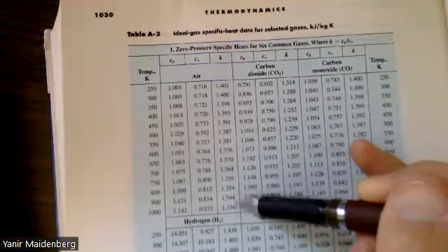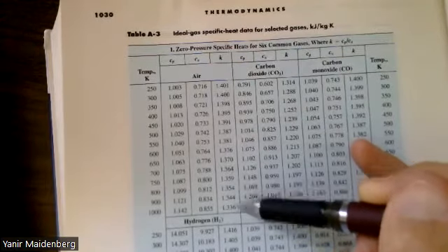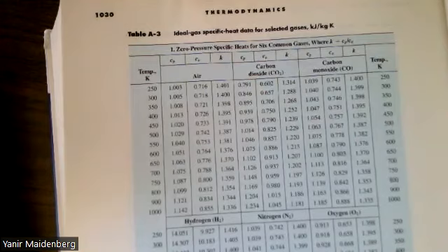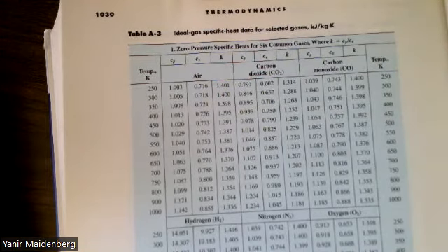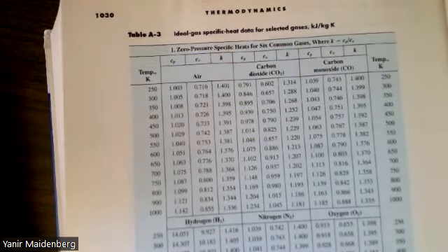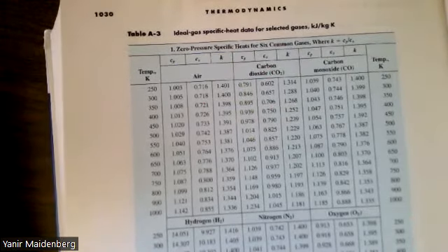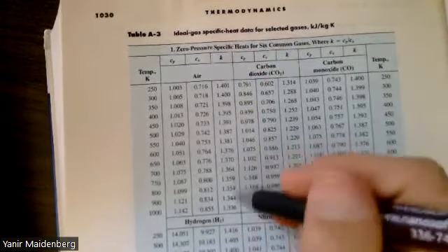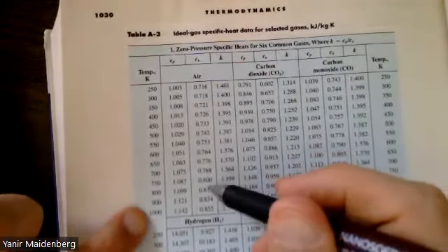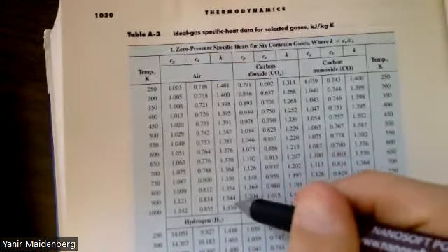So we can make an assumption that it's probably 1.35, 1.34, something like that. Will it change our trajectory here? Absolutely. But since we don't have any Cp and Cv data versus temperature, it's okay to make this sort of an assumption. We're going to use an average value between 800 and 1,000. Take it to be about 1.344.